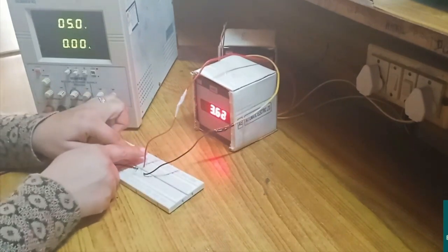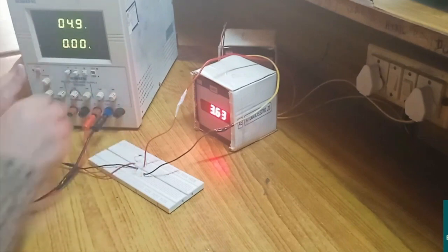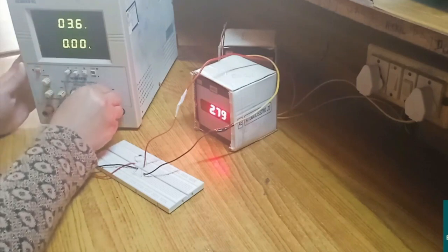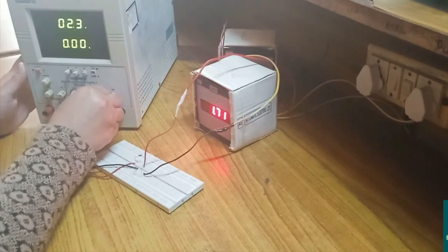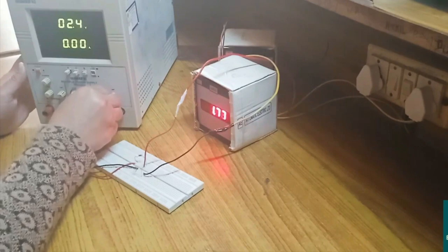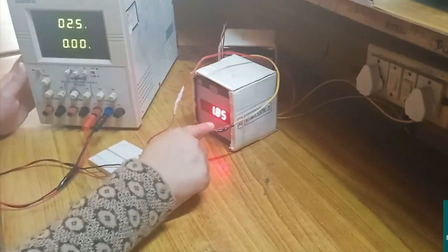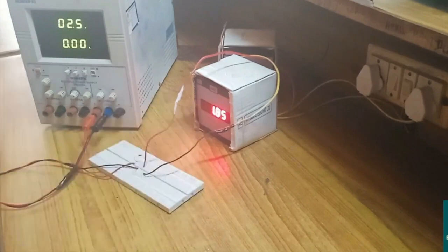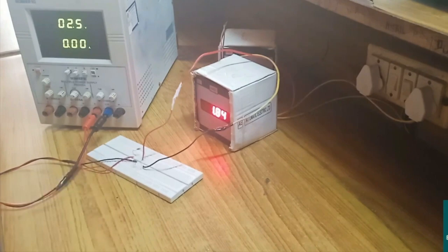VTH in series with RTH, in series with RL. So this must be set at VTH. So what was VTH? 2.5 volt. So let me just decrease its value till 2.5 volt. So now you can observe it, 2.5 volt VTH, we have got approximately the same value, 1.8. Hence, the current flowing through RL in step number 1 and step number 4, that is Thevenin's equivalent circuit, comes out to be equal to each other. Hence, Thevenin theorem has been proved.